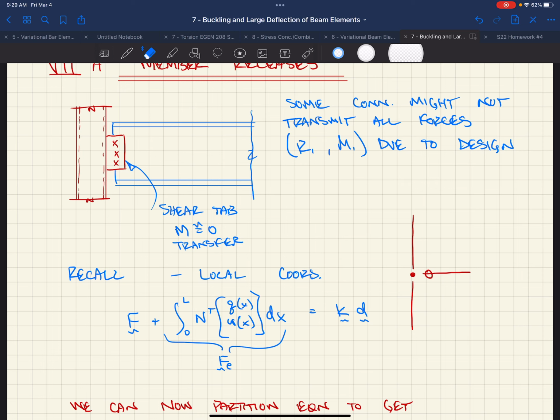You have to start looking at, okay, now you have this unbraced length of the column wall, and that could buckle potentially, right? I've had it in some places where we had to beef this up or put plates on the top and bottom, because the unbraced length of 3 inches wasn't enough, because we had hundreds of kips trying to go through this. Hundreds of kips of lateral? Yeah.